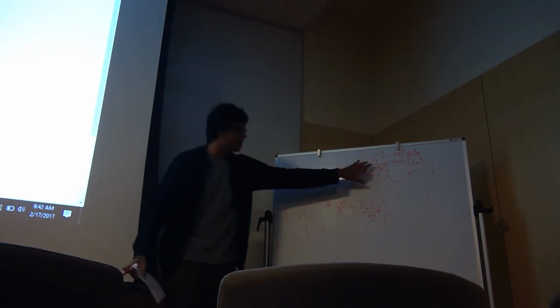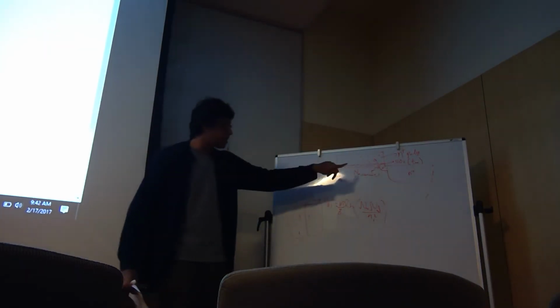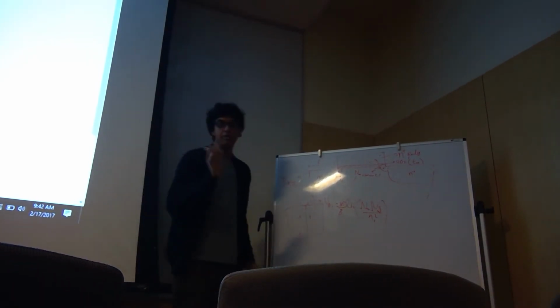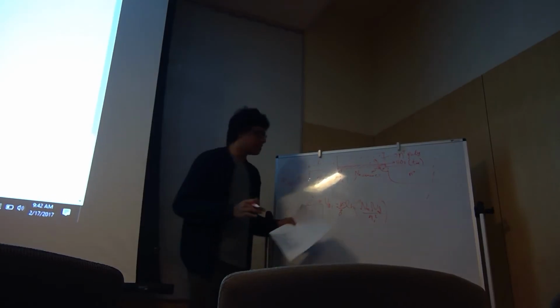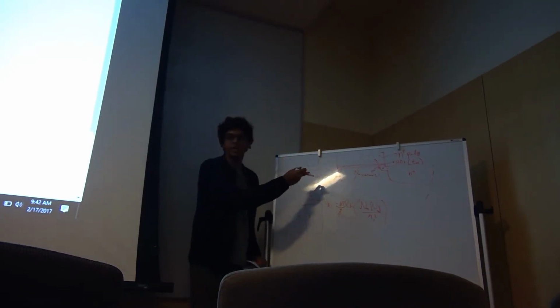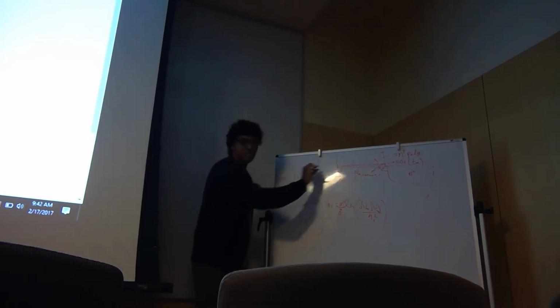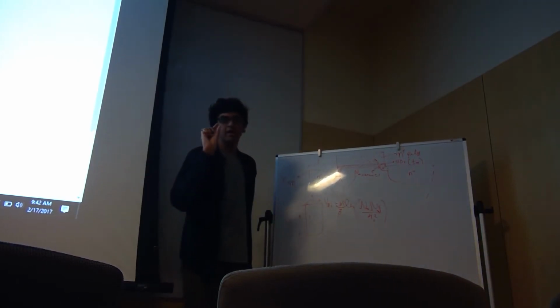And that can actually accumulate charge here, and by accumulating charge here, you can actually change your threshold voltage. Okay, so there are a lot of non-idealities in this transistor. So that's generally why you would make this region lightly doped. And the reason, okay guys, you need to make this as shallow as possible, okay?